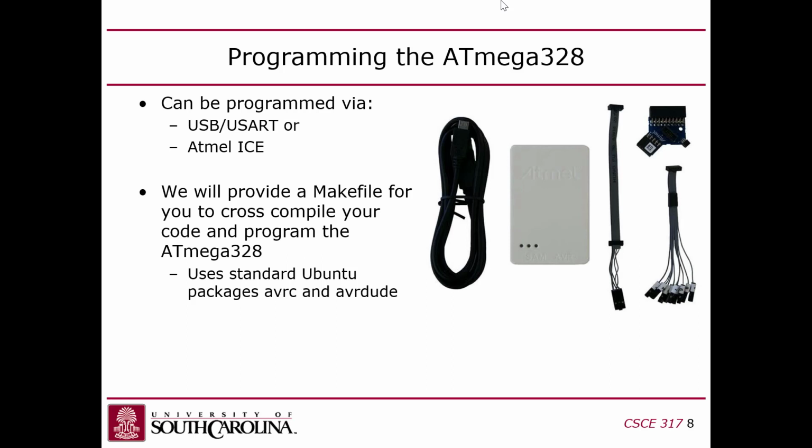There's instruction set emulators, but I don't think they emulate the peripherals, and certainly not the external peripherals, right? That is the problem: if you are interfacing with, say, a screen, there's not really a way to do that. But there is one that claims to support all of the built-in peripherals, but I haven't tested it yet, and it looks a little complicated to set up. Well, that was a student project too, wasn't it? Or it was somebody's master's degree, basically. Yeah, AVR, Atmel, the company that makes the chips, they don't provide, as far as I know, any way to simulate it.